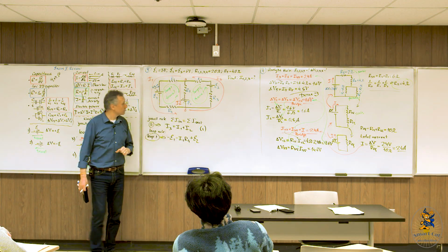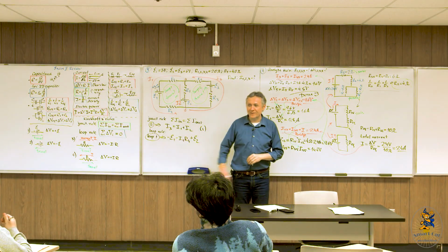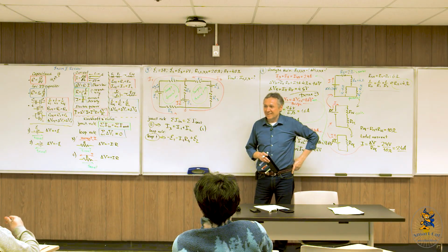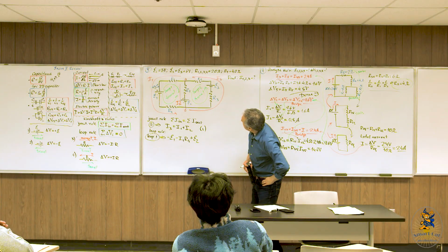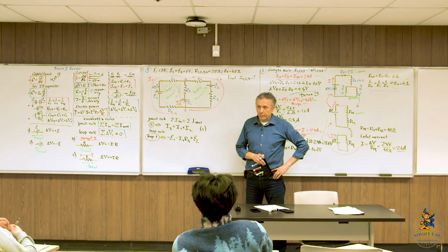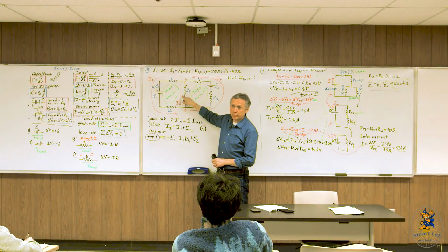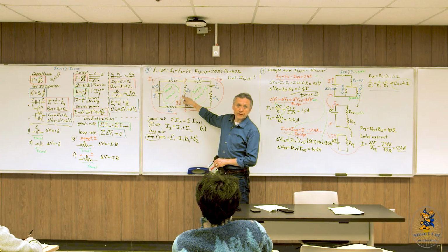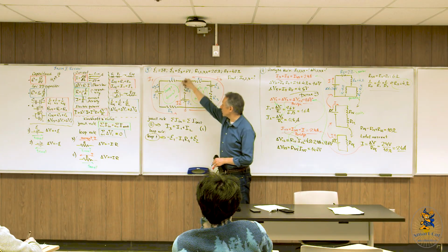Great. So now this resistor, R5. What will be the contribution? I'm moving away from the rules. It's positive: I2 R5. Now the current is I2, and that's another typical place for mistakes. Sometimes students still use current I1, but now it's current I2.